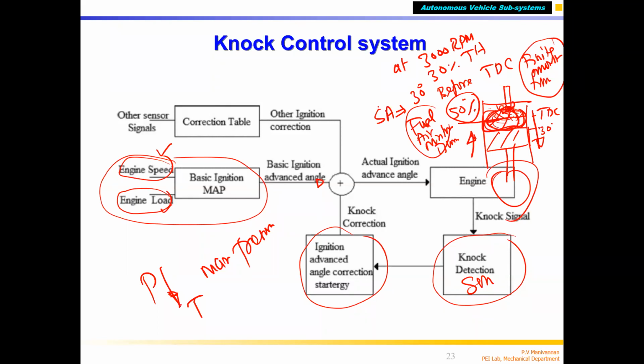So it takes some time. It can be 1 or 2 milliseconds, depending upon the compression ratio, the air-fuel ratio, all these things matter. But the average is, for example, 1 millisecond or 1.5. That much time you have to give. Now, if the engine is running at 3000 RPM, we know that the compression stroke takes 2.5 milliseconds, as the piston moves from BDC to TDC, compressing the air-fuel mixture.